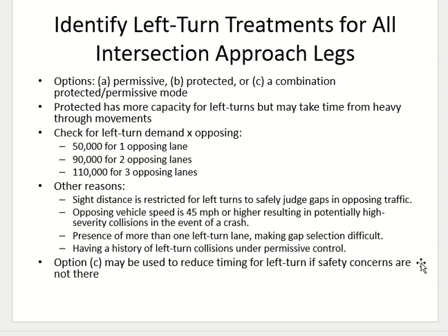Presence of more than one left turning lane. So there are two lanes for left turning, then it's too risky to make it permissive. This driver may not decide, but the other one decides, or both of them decide at the same time. So with more than one left turning lane, the left turning should be protected. Or you tried permissive and you saw there were crashes.